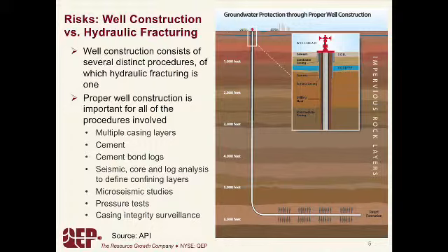And there are some things that we've done and that we've learned from our experience in Wyoming that I'll share with you. First of all, when I think of hydraulic fracturing, I think of it as part of a continuum of the well construction process. The drilling of the well is the first part. We move in a drilling rig, we drill a hole in the ground, we cement steel casing in the ground. When we cement it, we actually pump concrete down the hole and out around the outside to cement that steel casing very tightly in the rock.